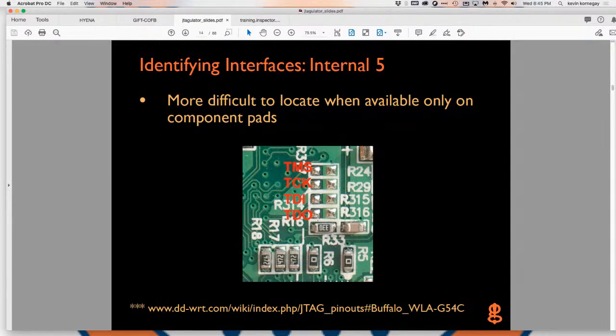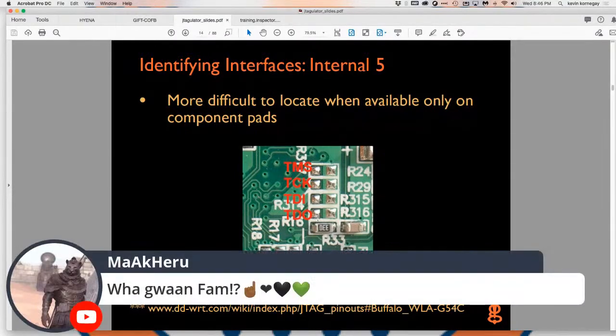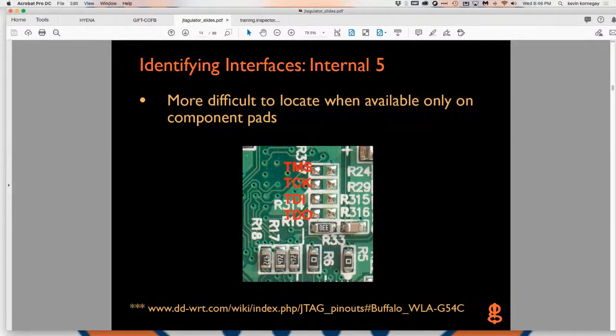It doesn't release the channel or the data until it receives an acknowledge signal back from the receiver. So it sends the data, the receiver gets the request, goes off and processes that data, and when it's done processing, it asserts an acknowledge, so that the sender can send the next set of data.